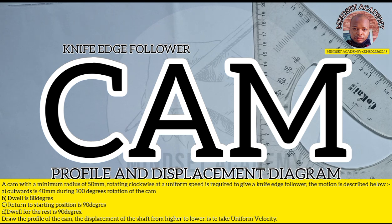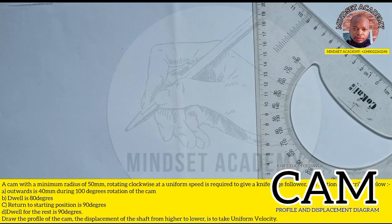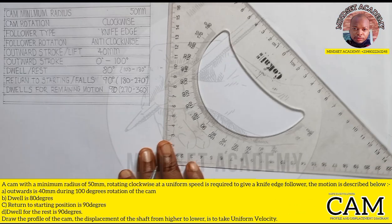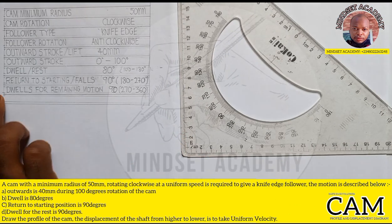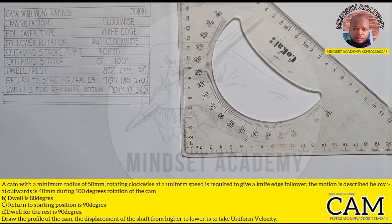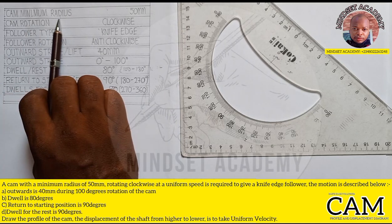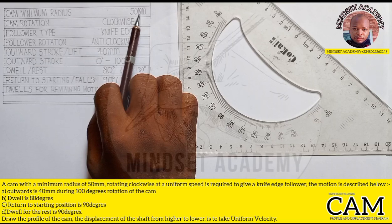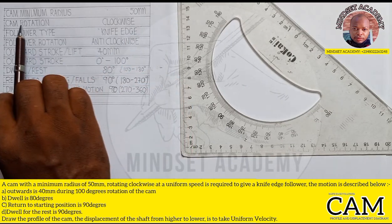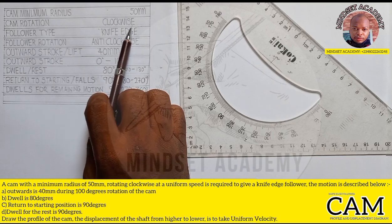So the first thing you have to do, you have to tabulate this, put it in a tabular form, right? And that is what I am going to do now. This is an important part of it. We have to draw the table and put in all our parameters. If you look closely, we have the cam minimum radius, which is 50 millimeter, right? We have the cam rotation, which is clockwise, as shown in the question.